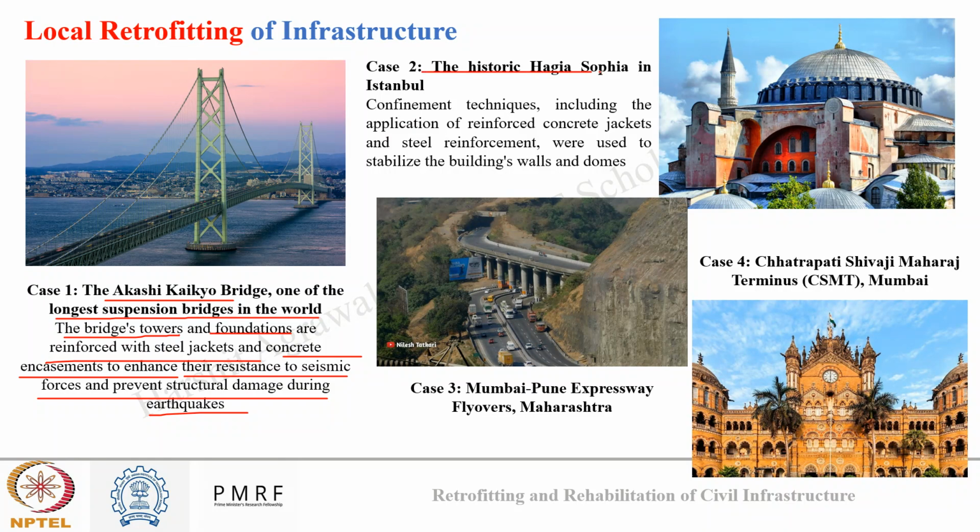Then there is a historic structure in Istanbul where confinement techniques, including reinforced concrete jackets and steel reinforcement, were used for stabilizing the building's wall and the dome. So here also local retrofitting measures were used.